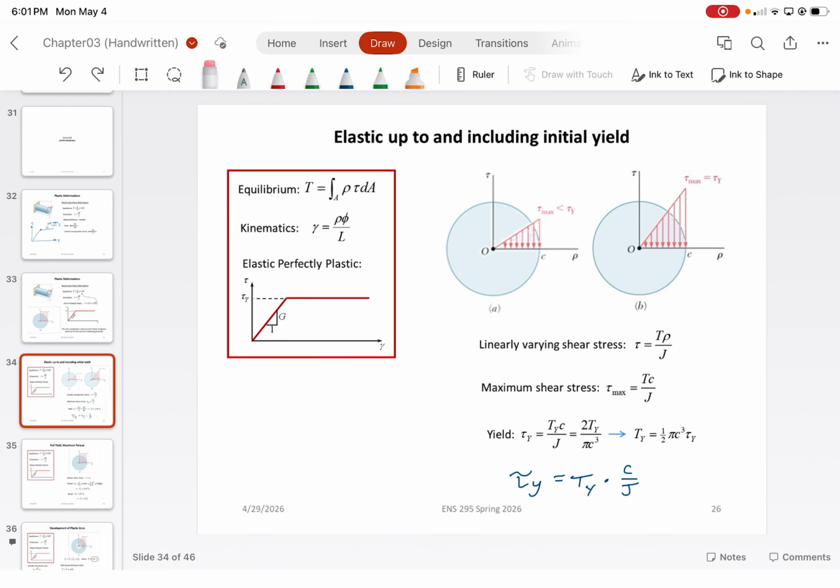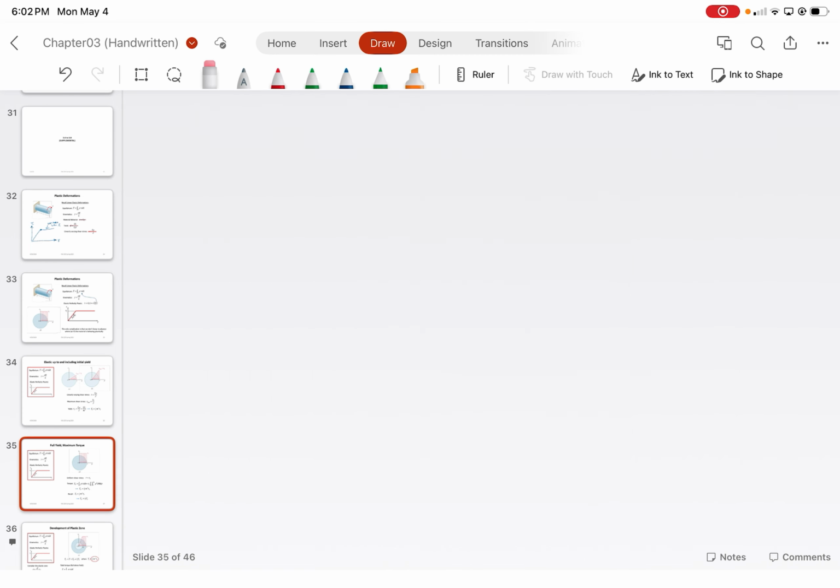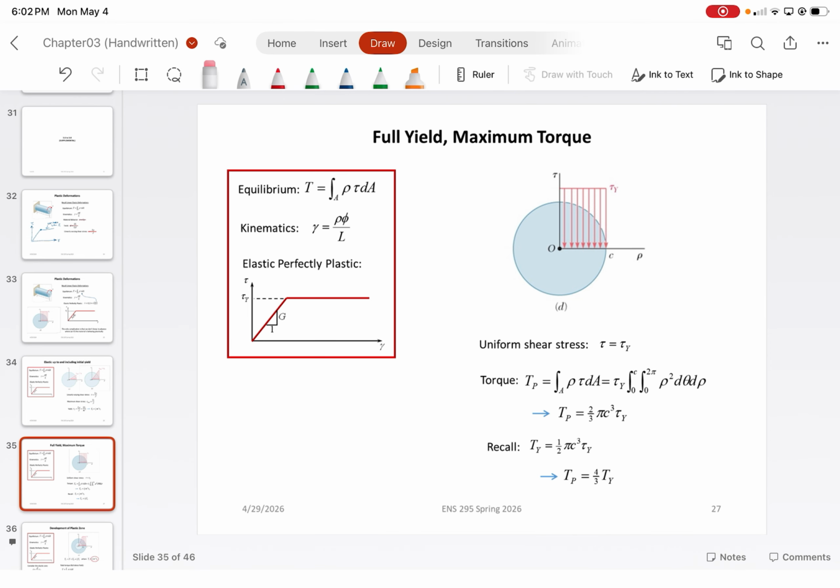All right, that's given right there, T_y being the torque that's applied. So if you were gradually increasing the load more and more, you can iteratively figure it out. But of course, once you reach, for example, the yield strength of 21.6 ksi that we had seen for A36 steel, now we need to consider the next regions.